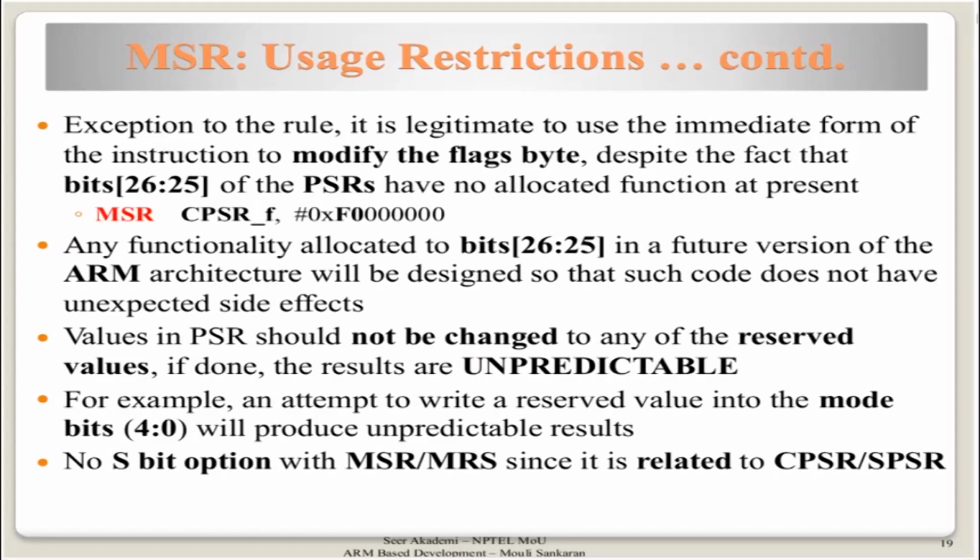And one more thing, if you recall, there is no S bit option here, because we are doing something with MSR and MRS, which deal with CPSR and SPSR. There is no S bit, or you cannot say MRS with S. There is no special suffix S, you cannot mention it here.